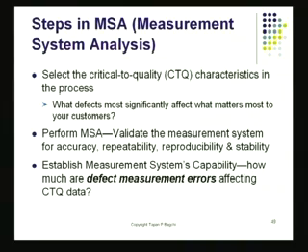Once you've done that, we've also got to make sure that I establish the capability of this measurement system. It by itself should not introduce so many errors that parts per million figures, when you try to measure them, are wrong. It should not be like that. So it's a very important step. In fact, before you go into your improvement step, before you start making measurements and so on, make sure that the measurement system you're applying to produce data out of the process is worthwhile looking at.